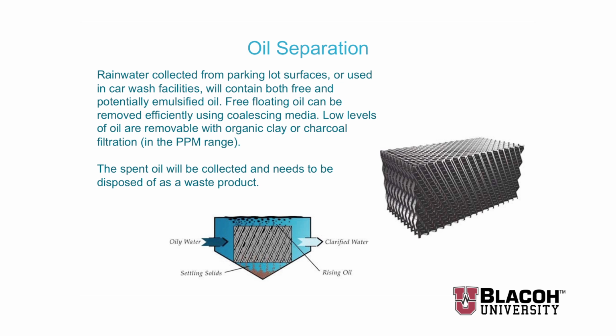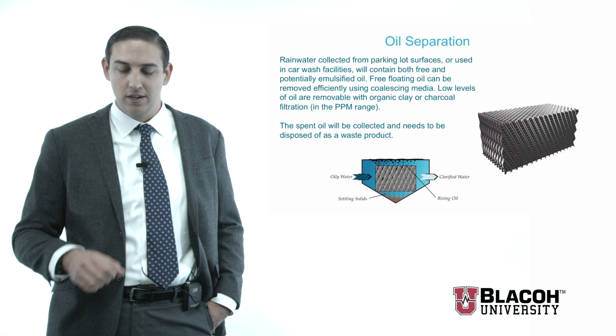So these may or may not be emulsified. Emulsified essentially is a substance which is not dissolved, but basically is chemically bonded to water. So if you see an oil-water emulsion, you cannot physically separate it, so they use what's called an emulsion breaker in a lot of those cases to break that oil-water bond. Antifreeze does that a lot. You probably see a very pretty color on the ground. That's because it's emulsified now in the water. You need to actually separate that and then take it out of your system prior to use.